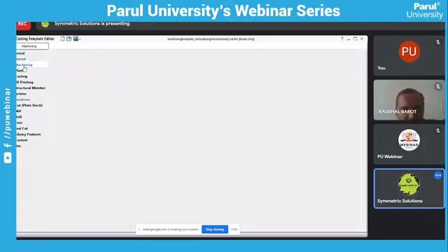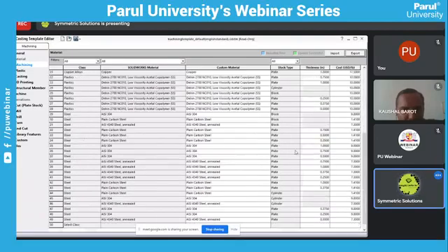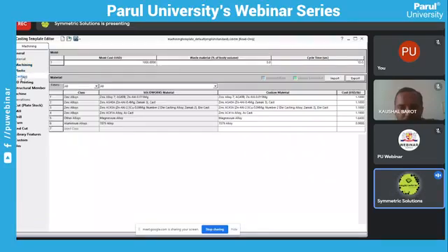And apply your real material cost here, like aluminum alloys, copper alloys, plastic, and steel. In steel, define block or plate. Your object stock type is plate as well as block, and thickness as well as cost. Cost right now we have USD per pound. Just define your value like INR per kg. Just change your value. Then these are the plastic materials, these are casting materials.